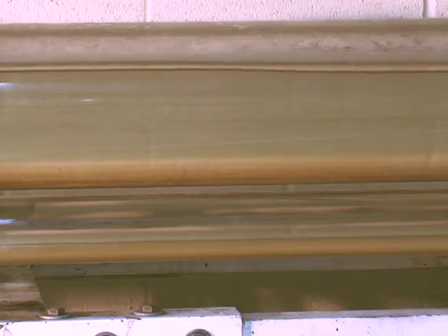In the flow loop now, there is 628 barrels per day of water being pumped through the tubes, and the airflow rate is 0. You'll notice in the large tube on top that at 628 barrels per day, the tube is not full. There is an air gap on top. This flow is characterized with the name segregated flow, and it is stratified, meaning the heavier phase, in this case water, is on the bottom, the air is on the top. The small tube underneath is full, and you will see occasionally drifting by an entrained air bubble.